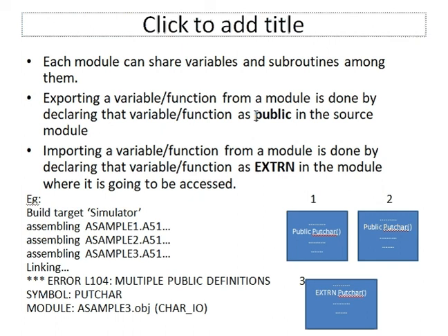You might have observed in the main program .asm file, we always use export main, and in the startup file, somewhere around line 250 or 260, there is the command import main. So the startup file is going to import this function which is addressed as export.